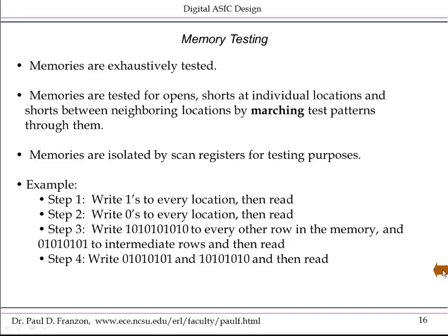You have a variety of memories in any modern chip design. These might be register files, which you saw an example of earlier, SRAMs, and embedded dynamic memories. In all cases they're organized, conceptually at least, like the register file example that we gave earlier. That is, we store one word per row of the memory, and we have multiple lines in the memory, and we'll read or write one line per memory cycle.